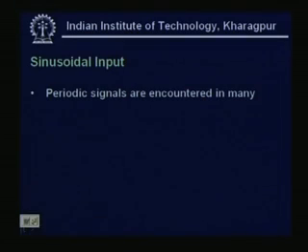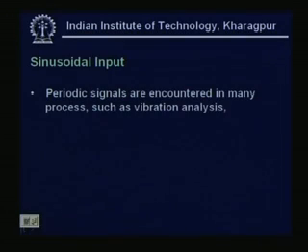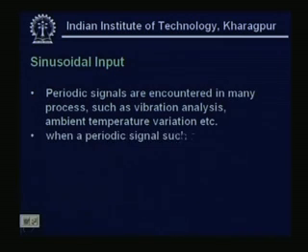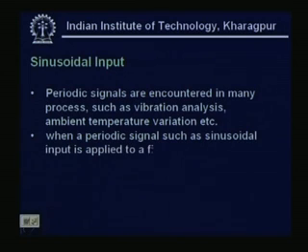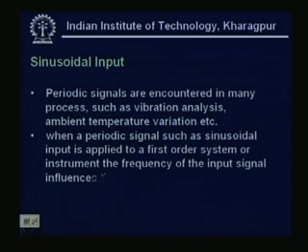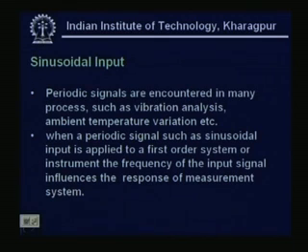You see, periodic signals are encountered in many processes such as vibration analysis, ambient temperature variation, etc. When a periodic signal such as a sinusoidal input is applied to a first order system or instrument, the frequency of the input signal influences the response of the measurement system. So, the frequency will control a lot of parameters, as we will find. So, frequency is of prime importance in the case of a sinusoidal input.